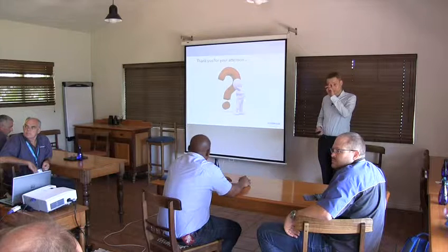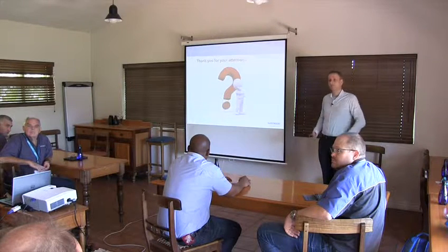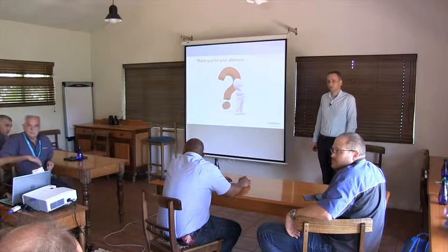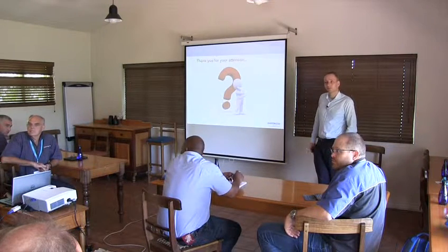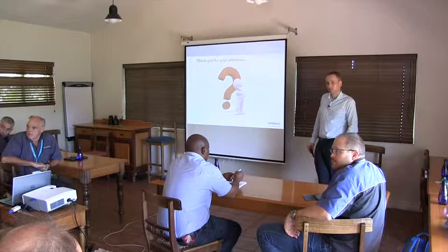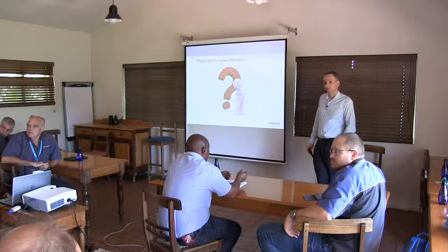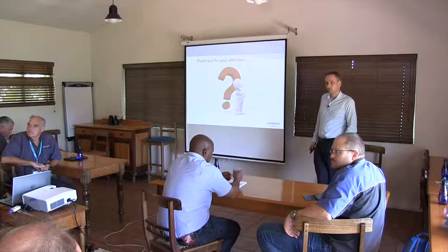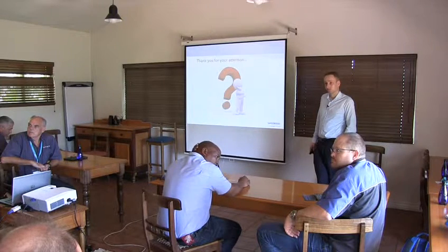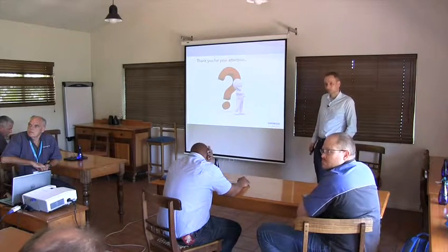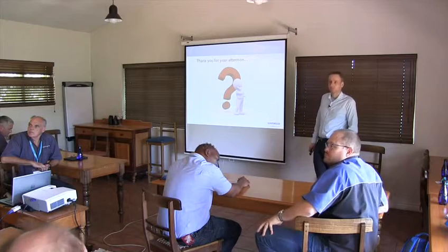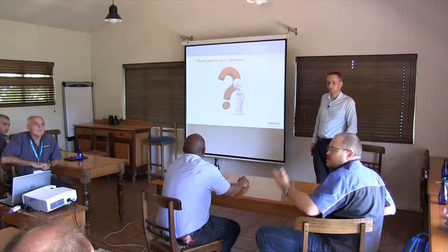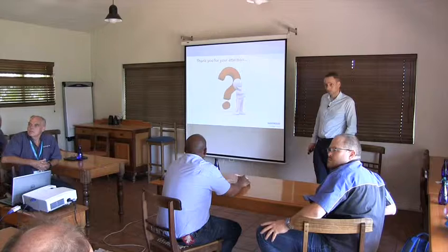But disinfection only works if it's being filtered. So we picked that up. There's two things. One is on large scale would be membranes, and then secondary would be a smaller scale where we want to get a tie-up with a local supplier of normal cartridge filters, for 5 cubes an hour or 3, that we can locally get at a very competitive price. Sign an OEM agreement with those guys and package it together with our Aquadam. So we are going to incorporate it from our point of view.